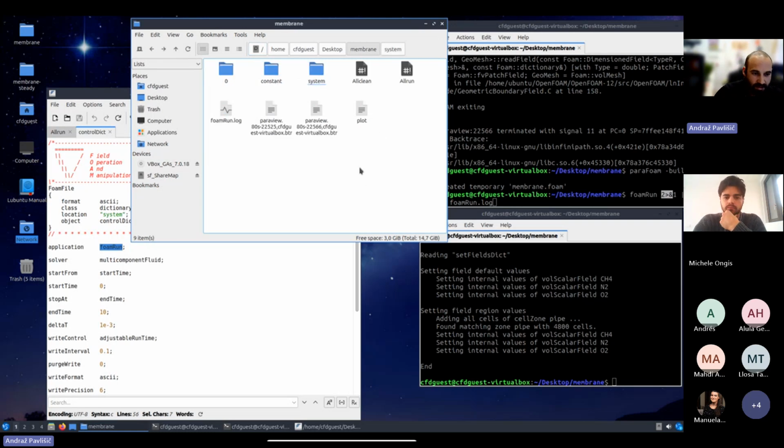Why do we want to do that? Because when you're running CFD, you want to follow your residuals. Residuals simply mean that it's checking how the convergence of the continuity is going on. Is there a change in the velocity field, and so on. And when everything is in steady state, if the problem is one we want to force to the steady state, that means that all residuals have to drop drastically from the initial conditions.